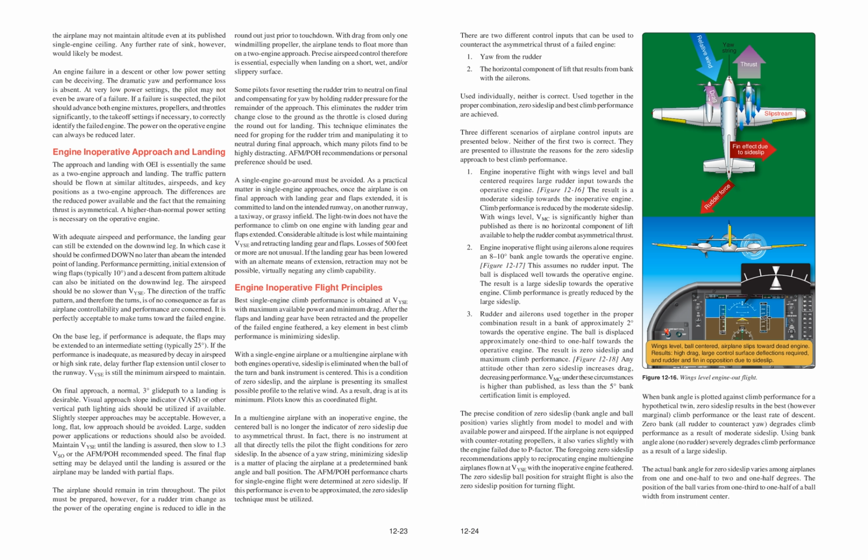Wings level, ball centered, airplane slips toward dead engine. Results: high drag, large control surface deflections required, and rudder and fin in opposition due to side slip.